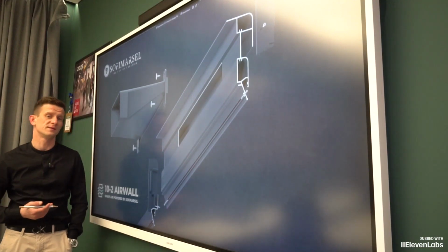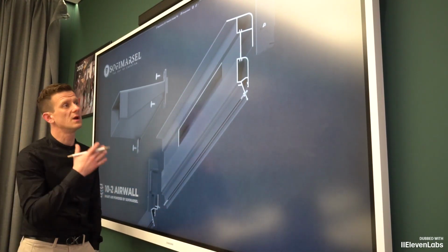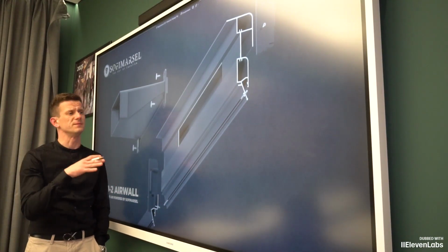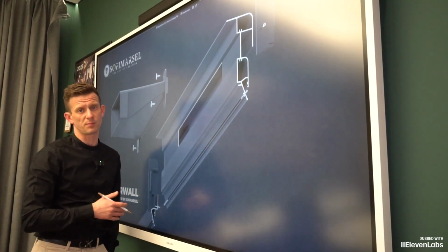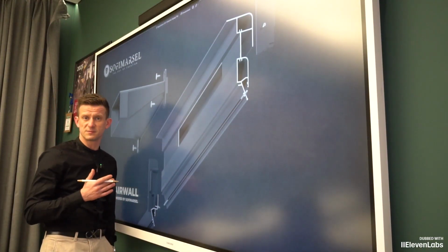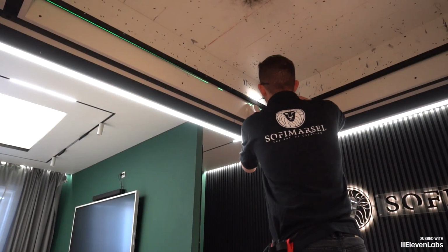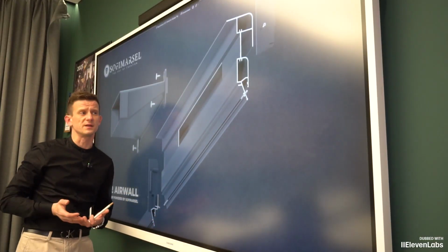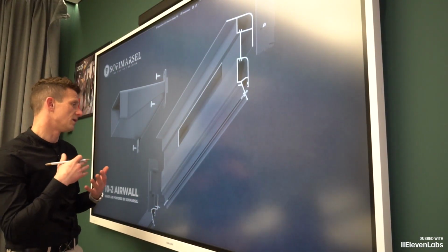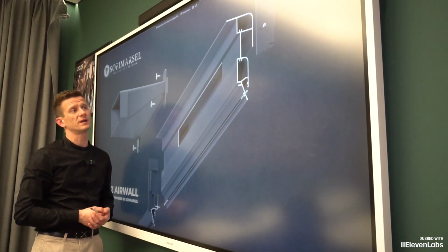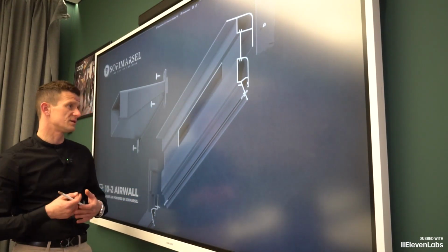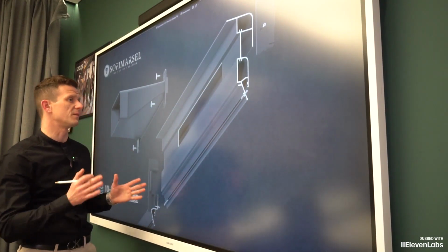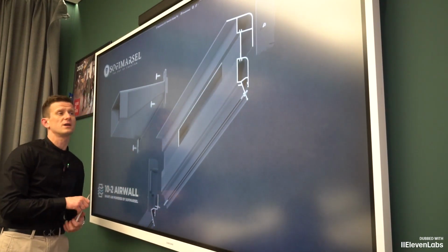We have the following system. We would like to introduce the new AIRWALL slot diffuser. This solution is a wall-mounted solution. It imitates the shadow gap formed on profile 0115, equal to 7.5 millimeters, but also represents a small static chamber. This solution is more suitable not for air conditioning the room, but more in that case is more suitable for concealed exhaust. An excellent solution for bathrooms, kitchens, if you want to achieve minimalism in your space. This solution is right for you.